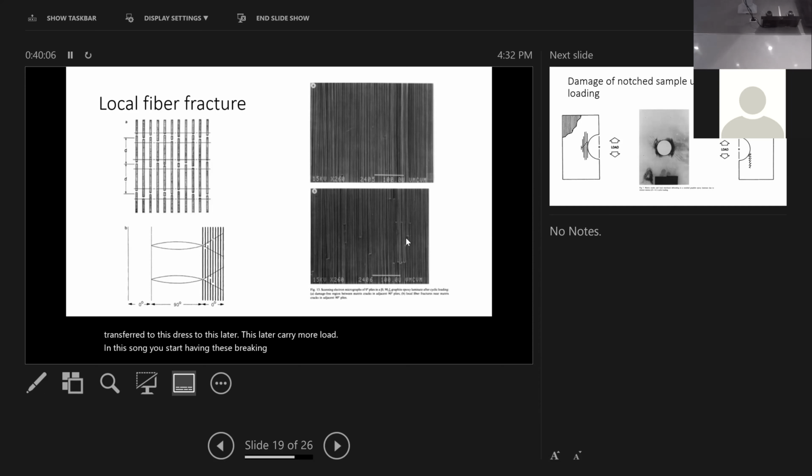So basically, that picture shows the SEM of a material in between the cracks and near the cracks. You see in between the cracks, very little fiber breaking. In this area, there is more fiber breaking. These are fiber breaks here. This is a telltale sign of fiber breaking: you see the free ends of the fiber. So that's occurring. So the other key idea that Reifsnider proposed is to divide layers in a laminate into